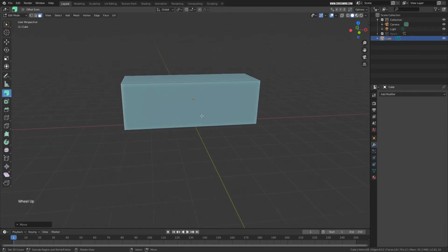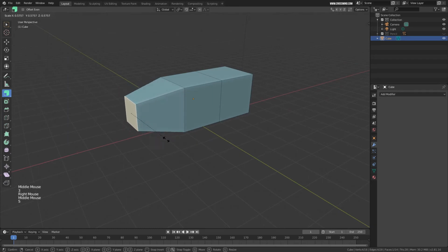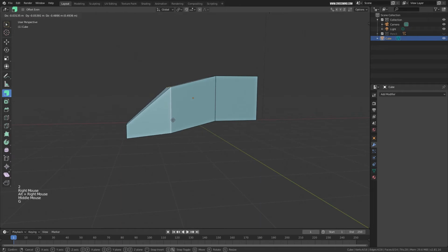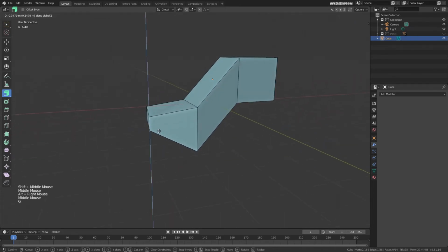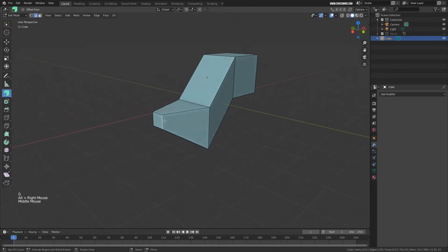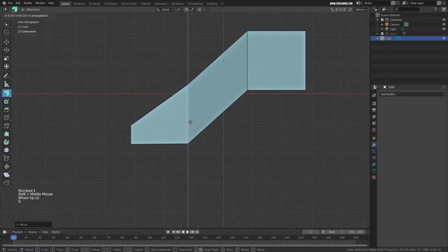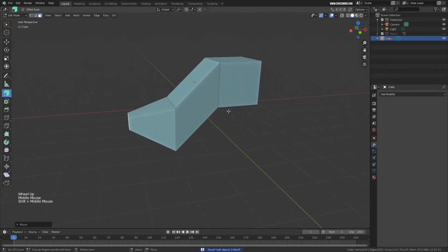What we need is, we definitely need more subdivisions over here. I'll press Ctrl R to maybe create 2 loops over here. Okay, and now I can select this face and bring this down like this, and select this entire edge loop. You can see how this is shaping up like a sandal already. I can select this face and move this down. In edge selection, with Alt select all these faces. Now I can start adding more details.